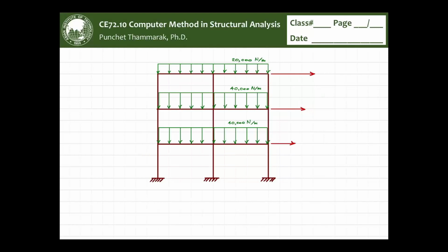A concrete slab, if it is 15 centimeters, is somewhere around 300-something, right? And then you average in the weight of the beam and the column. I think 0.4 does the job. It should be okay. It's a rule of thumb number to come up with something realistic rather than just putting 5-10 tons as a lateral load. So 0.4 times the 50 square meters, you get 20 metric tons for the weight of each floor.